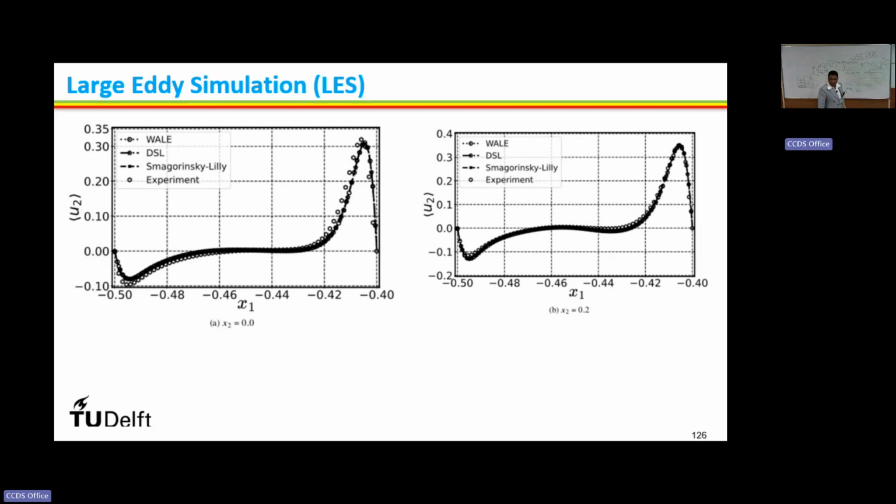Central difference alone is numerically unstable, and upwinding is not accepted, so they put some kind of flux limiter or boundedness on the central difference scheme. For spatial discretization of the momentum equation, bounded central difference is preferred for LES simulation.